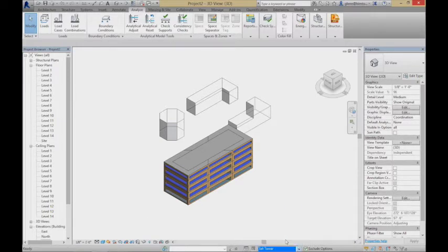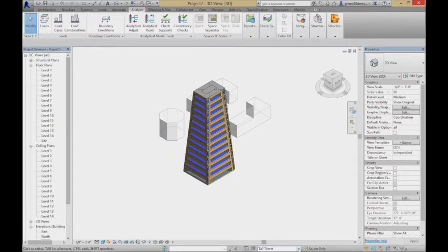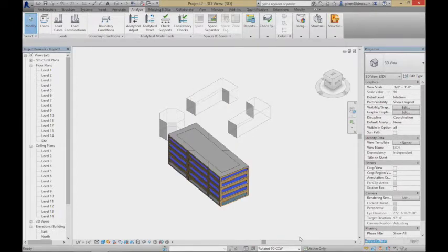Now the cool thing is it probably has already created the energy models for the other variations too. One of the nice things about doing it this way is as we make changes to the energy model assumptions, it's going to apply to all three of those alternatives. As opposed to creating three separate projects and having to carry those settings across to make sure we're using the same assumptions, design options let us apply the same assumptions to several different alternatives very rapidly. So that's a good thing.